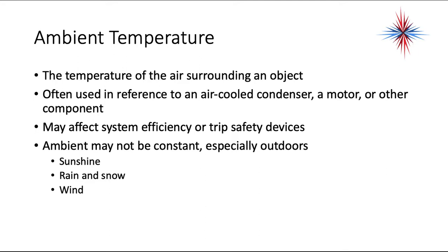The ambient temperature is the temperature of air surrounding an object. It's often used in reference to air-cooled condensers, motors, or other components. The ambient temperature will affect system efficiency and sometimes trip safety devices. Ambient may not be constant, especially outside.